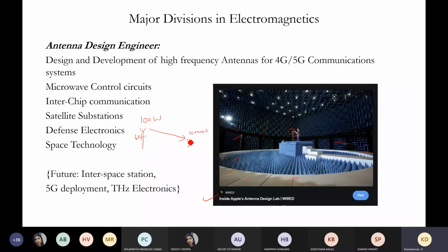Okay, so now I have improved my antenna system. It can receive 10 times more power. So it will now receive 100 milliwatt power. So by the way, I can cut down and send only 10 watt power instead of 100 watt power. Otherwise, the amplifier gain is supposed to increase by 10 dB, which means the power has to increase 10 times.